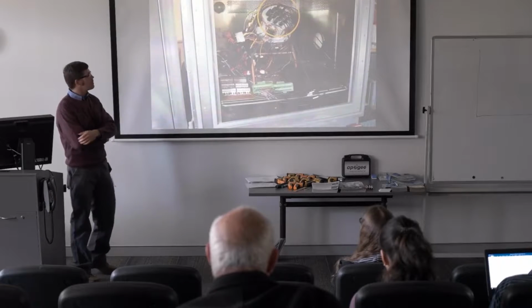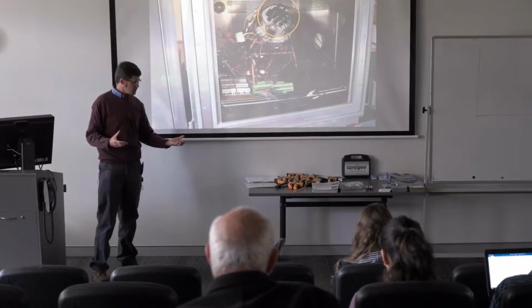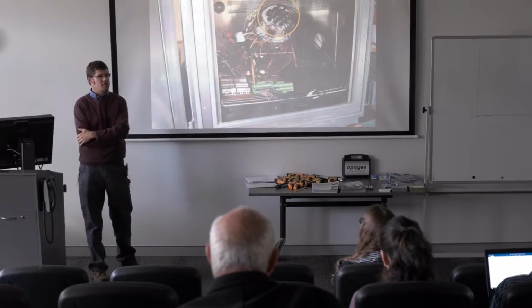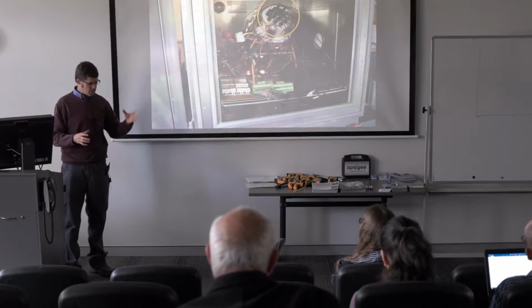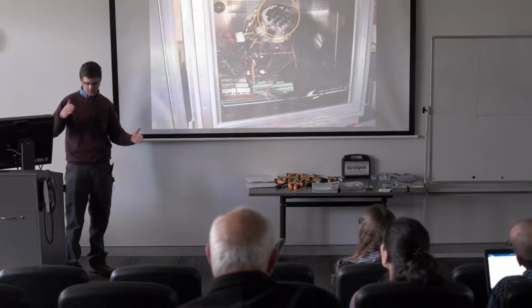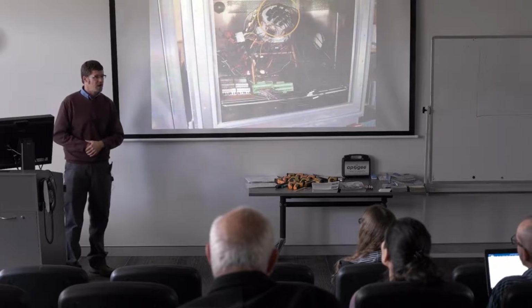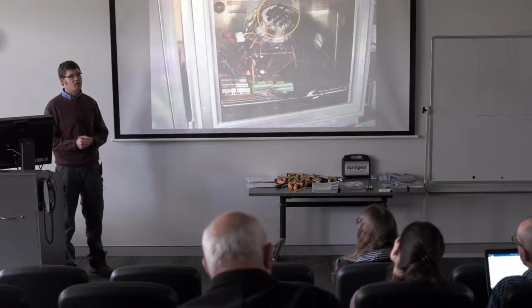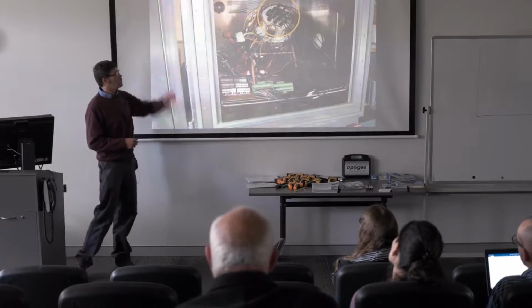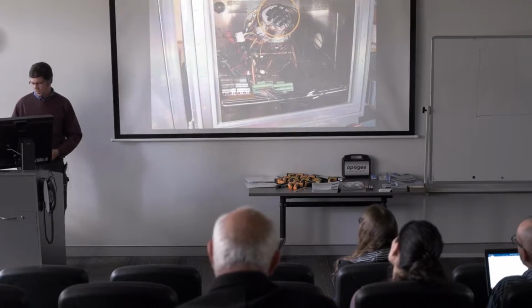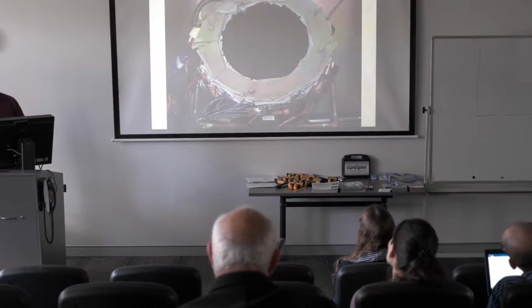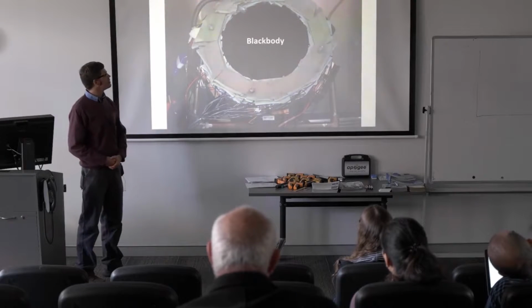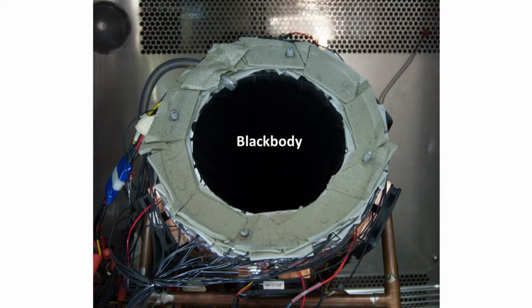independently control their temperature. And so what you have is a target, or the black body cone, and a cap that fit together, but we can independently control the temperatures of the two and set this temperature at one value and the sensors at a different value, and derive a whole set of data that allows us to get sensor-specific calibration coefficients for all the radiometers, and we can fine-tune it to 0.2 C uncertainty. So just to give you an idea, there's the actual calibration device with the cap piece pulled off of it, so you can see that it's a black body.